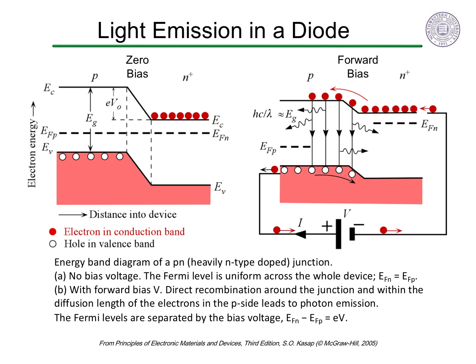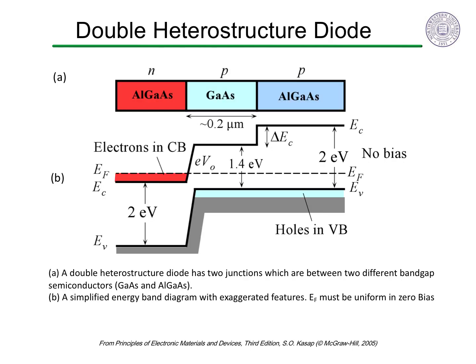ultraviolet light. One challenge is how to get the light out before it excites other electron-hole pairs, as the wavelength just produced will easily get absorbed by other parts of the semiconductor to make electron-hole pairs elsewhere. The trick used to produce the light near a p-n junction, but not have the light absorbed by the rest of the semiconductor, is to use a double heterostructure.